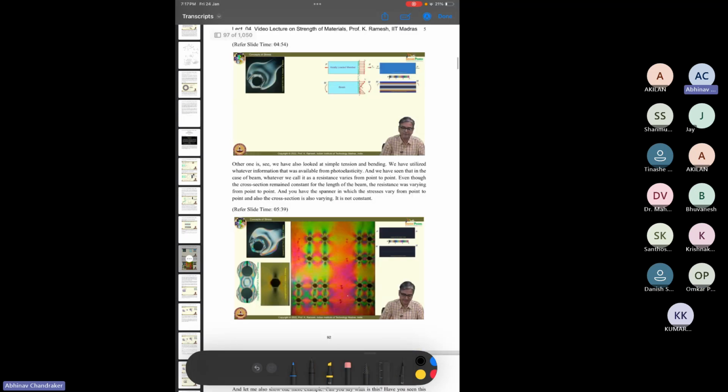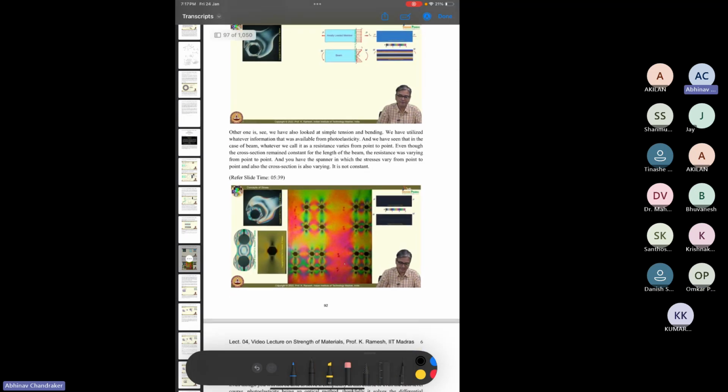But if you have a material which has some small holes in between, even though the portion of the material which is being removed in these holes is very small, the stress state developed near those hollow portions is not uniform at all. It will be very concentrated. So just near these holes, you will have a very high stress concentration region, and as you go away from it, it will become more uniform.